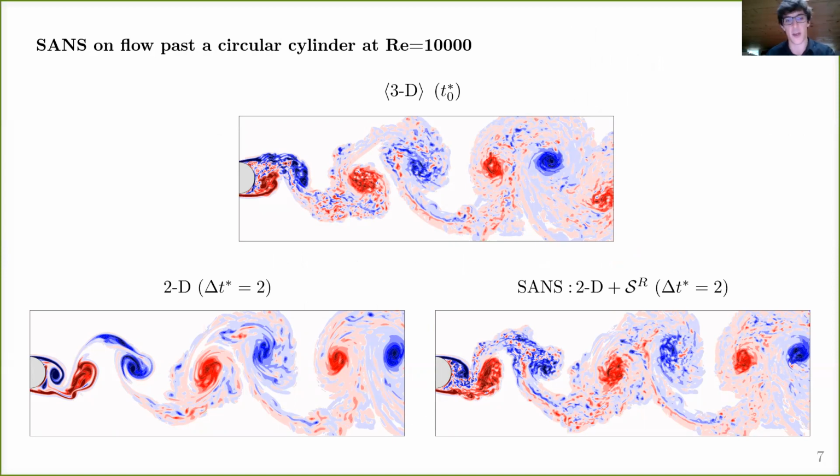You see how the wake has already rapidly 2-dimensionalized, and we see again the large-scale, coherent, energized vortical structures that in the end make you over-predict the forces induced on the cylinder. But on the other hand, when we include these closure terms, we recover the spanwise average flow, and we would measure on the body the correct induced forces such as lift and drag.